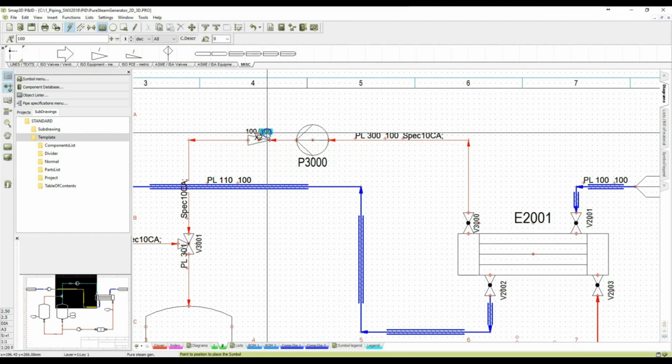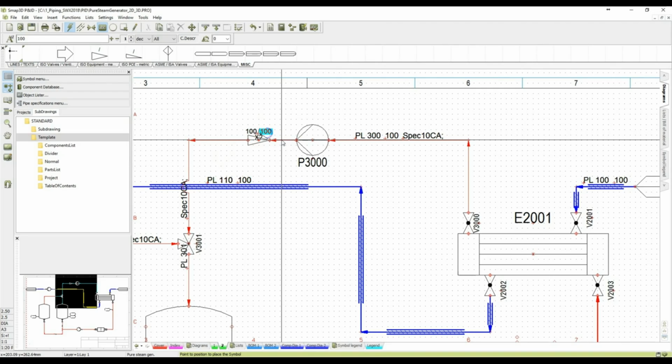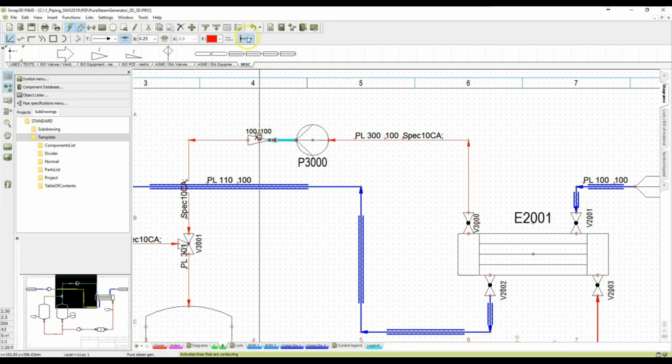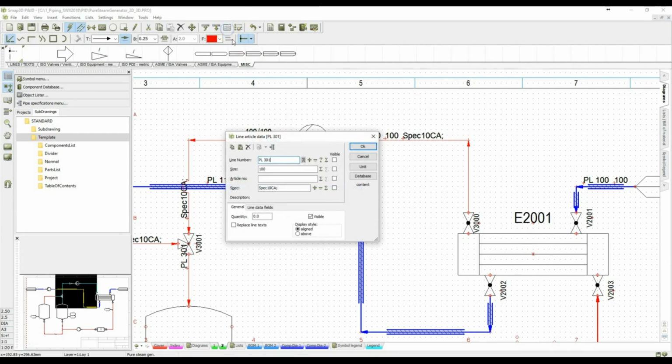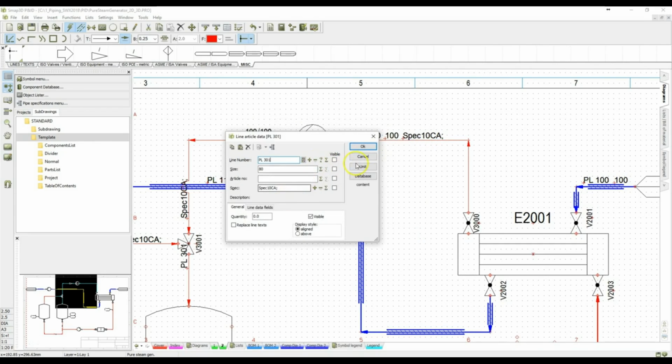100/100. Display diameter values are automatically taken from the existing pipeline attributes of the line where the symbol is placed. To correct these, you must change the diameter value on the line between the reducer and the pump connection. So we are going to click on this small line segment, and we are going to change this line segment size from 100 to 80. If we click OK, you will notice that the new information shown is